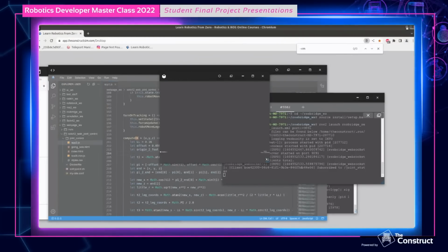So I guess ROS2 control, when you think about it, has two parts. One is the hardware interface, which talks to the hardware, sends whatever language the hardware speaks. The hardware interface both speaks that and also provides shared memory to controllers. And then the controllers are part of ROS2 control.